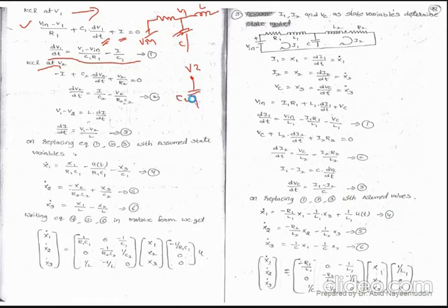For the given problem, you can refer to the node sum I already gave; the same problem I am solving here. The common element is I, and the direction of current I is in this way. If you apply KCL at this node, for the capacitor it will be C into dV/dt. For I, as the direction of current is incoming, minus I, plus the current through resistance R, which is V2 by R2. Now write the expression in terms of dV2/dt, and you will get the second expression.